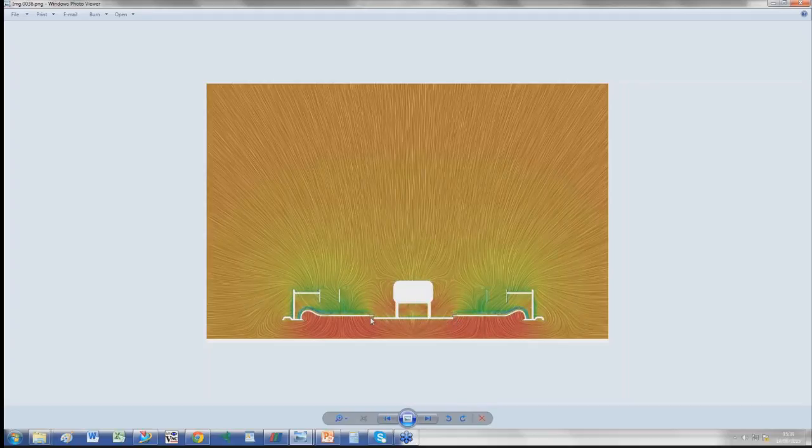It's what we call a neutral profile, and this is the FIA dictating this, up to Y250, so 250 millimeters away from the center of the car. And then you can pretty much do what you want in this area. So you will effectively create a wing that generates downforce. But it means that you have a big discontinuity here that will by itself generate a big vortex.